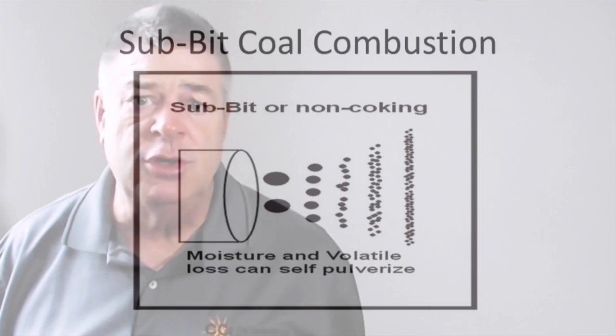That's a particular concern when you have good LOI or low carbon in the ash, and yet the pulverizer is making wall slags because the fineness is not right. So that's with subbituminous coals. That's one of the things we have to trust our judgment and our data from the coal mill fineness results. We might want to use those to guide us rather than the LOI number to look at the performance of pulverizers when using subbituminous coals, particularly if you're having heavy wall slags.